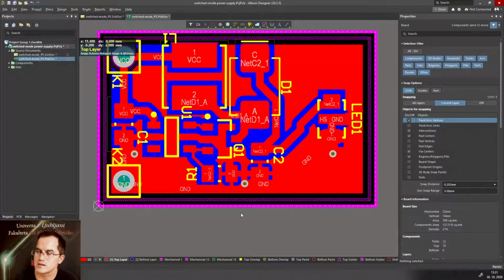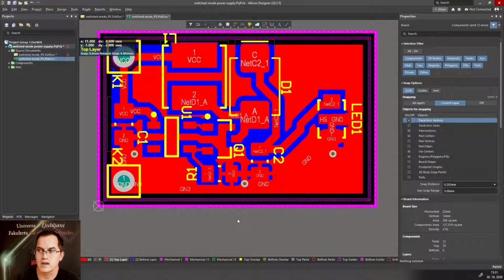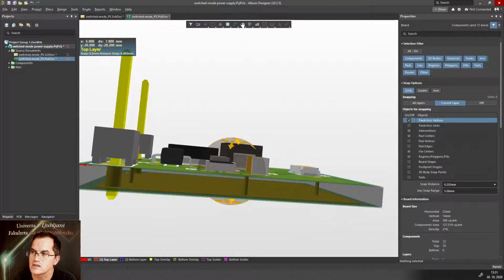So putting wires to connect to the bottom layer is essential for the device to be working also, so that the bottom layer is also acting as a good conductor for current. And therefore the current loops are no longer also on top, but actually the current is also flowing on bottom layer. And the area this current is actually taking can be much smaller then, because the area which they take actually is the thickness between the top and bottom layer.